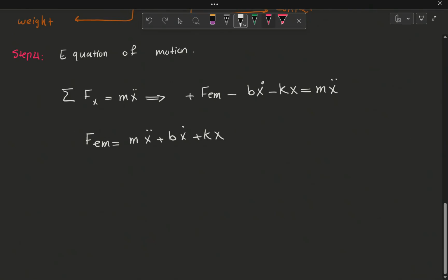Now look at this. There's one important test that I need to do before I box this equation. This is actually a sanity test. For this sanity test, I would identify the families of dynamic variables and see whether within a family I have different sign changes between the members or not. Look at the right hand side of this equation. You see that I have the family of x and its derivatives. And I have 3 members of that family: x, x dot, and x double dot. They all belong to the family of x.